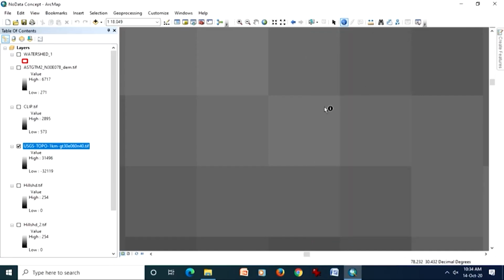You also might be knowing, this will also come in future discussion, but since we are having a demonstration, I will briefly touch on this USGS topo. This USGS topo global digital elevation model has been developed employing 250,000 scale survey topo sheets of various countries, and the contours from these topo sheets have been digitized, and employing interpolation techniques, a global surface has been created at 1 kilometer resolution.